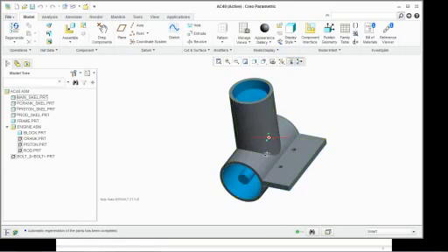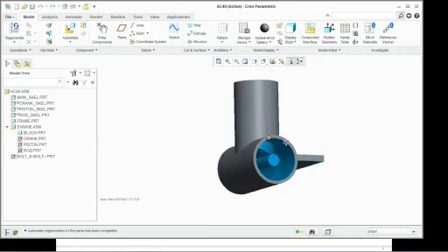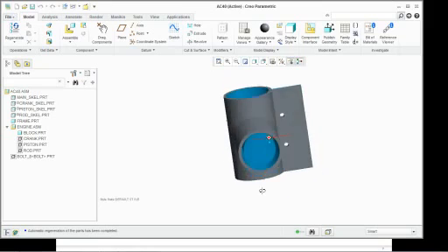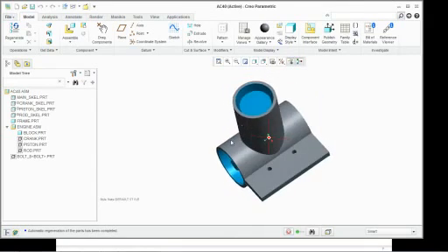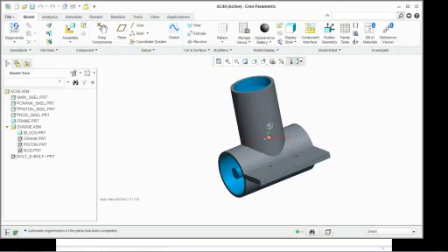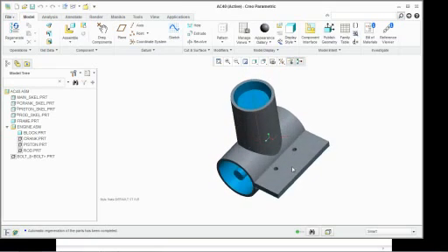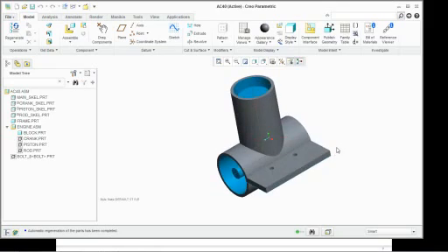Everything in this assembly mates to the skeleton. So notice that this component here did not get longer. The piston is not referencing that other diameter, it's referencing its own skeleton, so it's not going to get bigger unless we edit that skeleton. But everything did update dynamically.